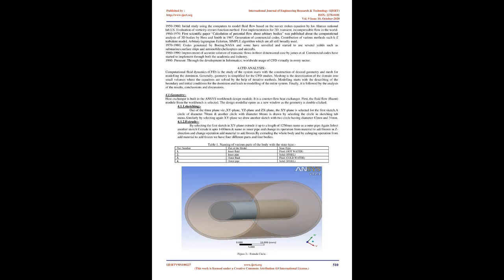Geometric parameters are annulus radius ratio, 0.3 to 0.5, fin height / annular gap, 0.33 to 0.67, and fin spacing / annular gap, 2 to 5. Flow parameters are Reynolds number, 100 to 1000, and Prandtl number, 1 to 5. Comparisons are made with a plain tube annulus having the same length, heat transfer surface area, volume flow rate, and